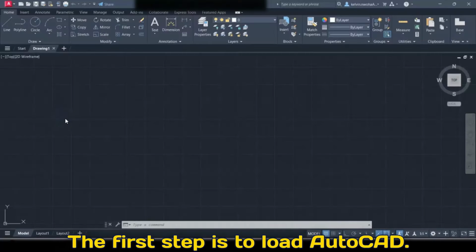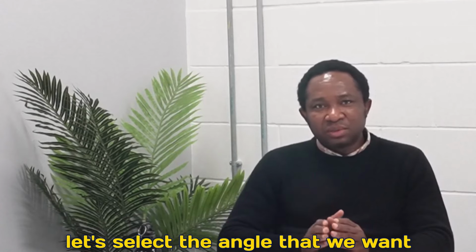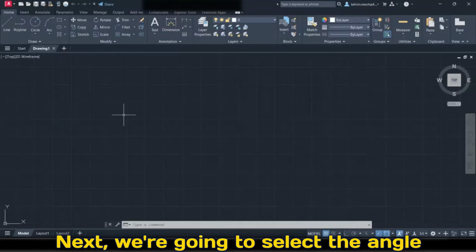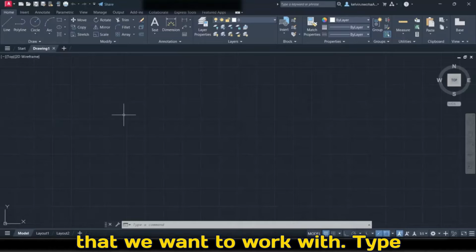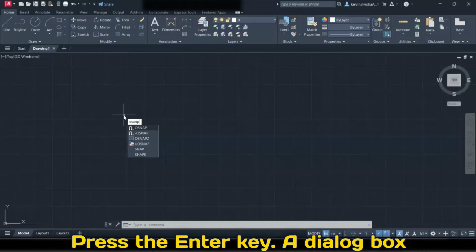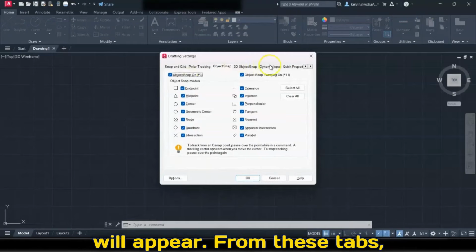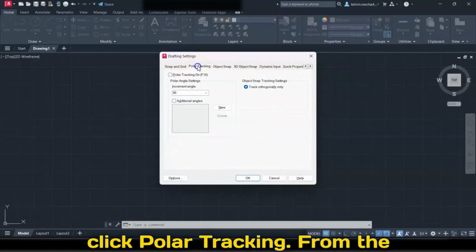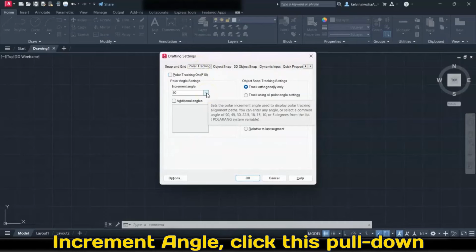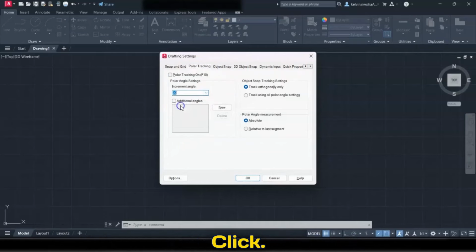The first step is to load AutoCAD. Before we get started with the drawing, let's select the angle that we want to work with. Type OSNAP, O-S-N-A-P. Press the Enter key. A dialog box will appear. From these tabs, click Polar Tracking. From the Increment Angle, click this pull-down menu and choose 30 degrees. Click.